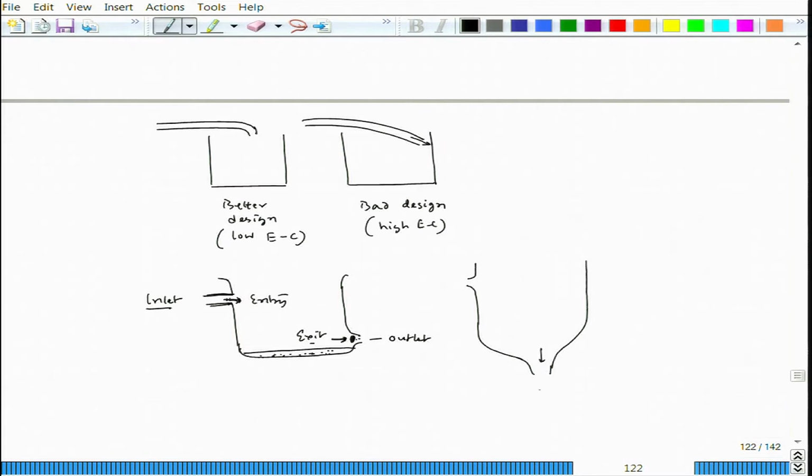at least in this case the bottom deposit of those dust particles would be much less, because with the flow of water those dust particles will go through the pipeline. And here is a gravity effect, and that gravity effect also allows less amount of clogging in this case, okay, but here the clogging would be more, fine. So, if we can stop the clogging, then definitely the flow would be laminar, there will be less turbulence and less erosion corrosion. So, this is another design aspect one can think of.